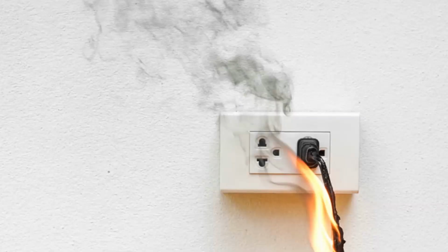Now, the standard colors on these wires are: live is red or brown, neutral is usually black or blue, and ground is green or green and yellow. Cables also have current limits, and this should be taken into account when you're planning your lighting for a show. For example, you do not want to overload the number of instruments that you use on one cable. It could cause the circuit breaker to trip, or worse, burn the wiring insulation, causing a short and possibly a fire.